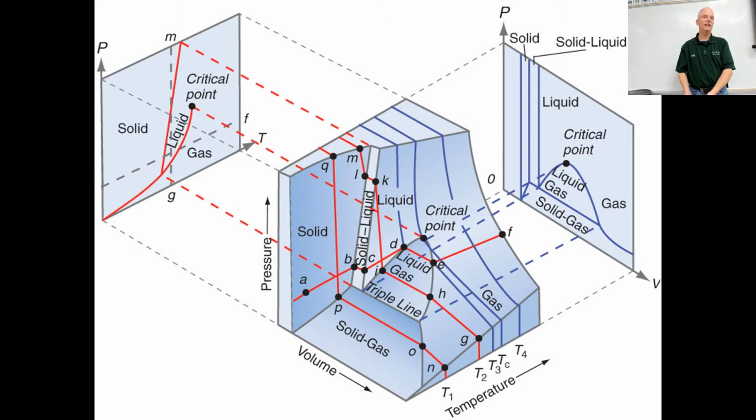Isn't that amazing? They actually change the gasket seating surfaces and everything. There has to be precision in construction down at the ocean floor. They can't adjust it down there. They have to build it and take into account the compression from the seawater. Think about the different materials you're using. You take the steel down, you have a gasket. Down there, your steel compresses a little bit, but your gasket compresses a lot, and now you're not even sealing. Exactly. And then they have rubber gaskets too, and those change a lot. That's a nice effect.